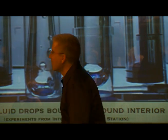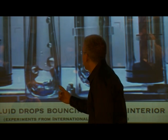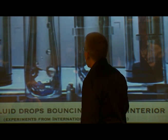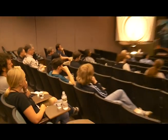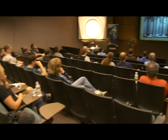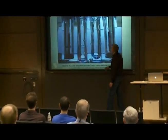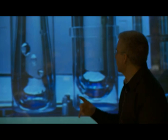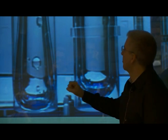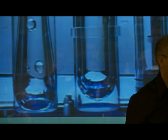So I'm going to run this again slowly, and here's what I want you to do. I want you to concentrate on the areas at the bottom of each of these tanks. So let's see if I can do this. Okay, there we go. Did you see it? I'll do it one more time. What I'll point out is what happens if these tanks, they're slightly different shapes. When you shake them slightly, it turns out the one on the left generates a jet up through the center. You get a cylinder of fluid, it breaks up into drops due to the Rayleigh instability. The one on the right has been engineered to damp out that mode of oscillation.